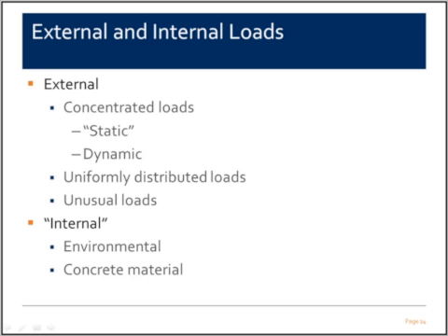The internal category, I called it, there are the environmental effects, which could be temperature and the moisture variation. And shrinkage of concrete material and carbonation of concrete material could cause internal loading. I called it internal loading, but it causes stresses, as we've seen earlier on the slab itself.